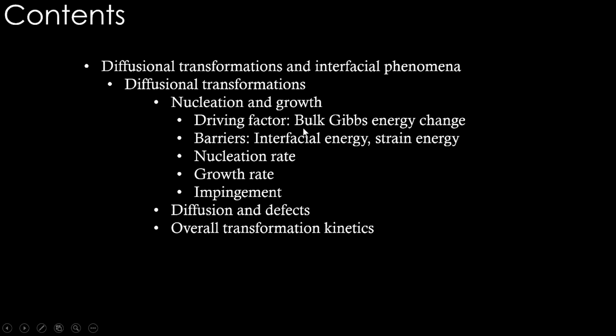Bulk Gibbs energy change is the Gibbs energy change that we have been considering till now as the driving factor for diffusion. That aspect will be there, and on top of that there will be barriers for nucleation and growth, which are called interfacial energy and strain energy aspects. Then we will see how nucleation rate depends on all this. Now we are talking about rate, and kinetics will come into the picture here. Then growth rate and phenomena such as impingement, which also must be considered.